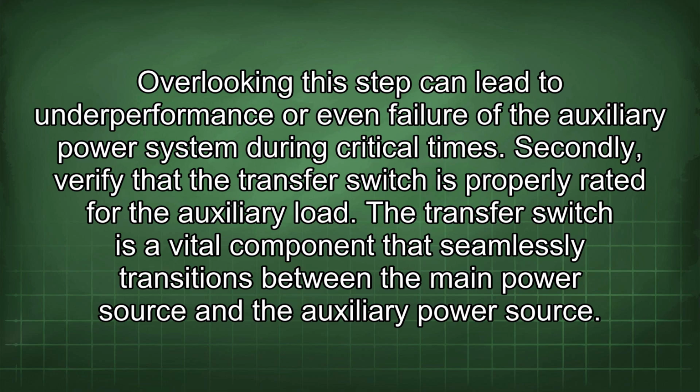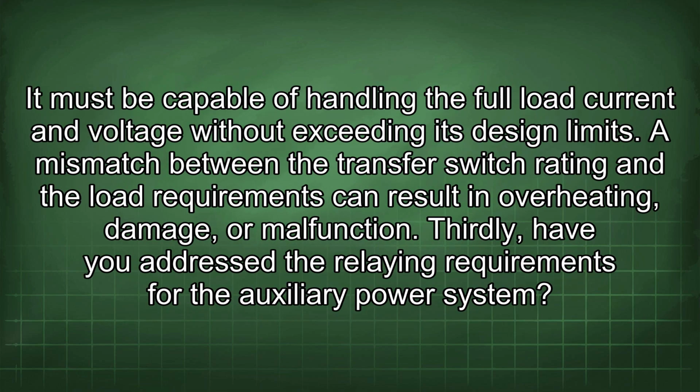Secondly, verify that the transfer switch is properly rated for the auxiliary load. The transfer switch is a vital component that seamlessly transitions between the main power source and the auxiliary power source. It must be capable of handling the full load current and voltage without exceeding its design limits. A mismatch between the transfer switch rating and the load requirements can result in overheating, damage, or malfunction.